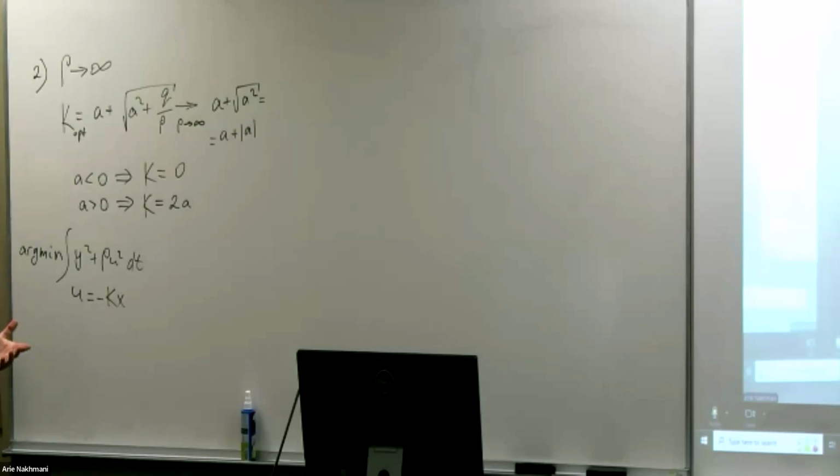So if it is stable in open loop, which means it converges by itself somehow to zero from initial conditions, whatever they are, just keep it going. Don't give it any input. Give it input 0, practically speaking. So your controller will automatically produce 0 input to your system. Nothing. Don't touch it. Let it converge by itself. You will not need to invest any energy in the system. So it automatically will happen by that type of controller.